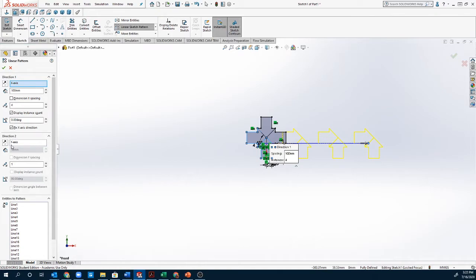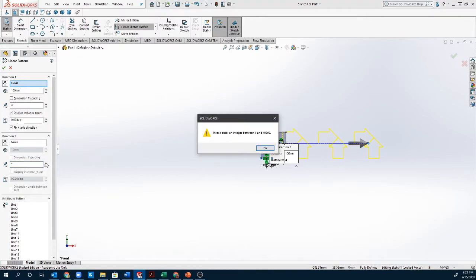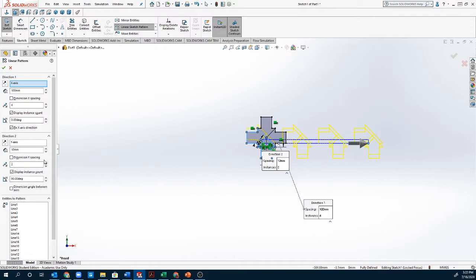You can also then go in the y-axis. All you need to do to activate the y-axis is, instead of saying that you need 1, just increase that to 2. Like this. If you try to go below 1, you're going to get an error, as you've seen. Now, we can also set that the distance here be, say, 100. The other thing you can do is use these angle definitions. So we can say that the y-axis is going to just be 45 degrees, for example. And what it'll do is it'll tilt it at 45 degrees.